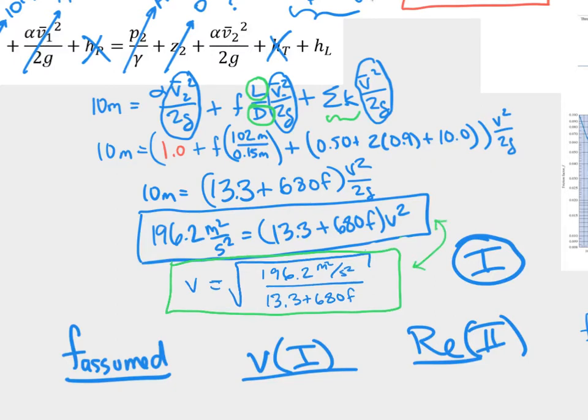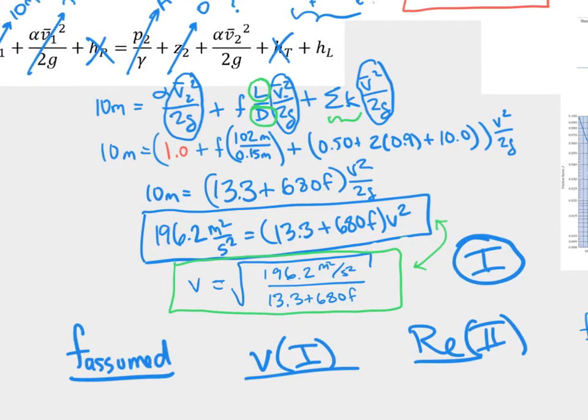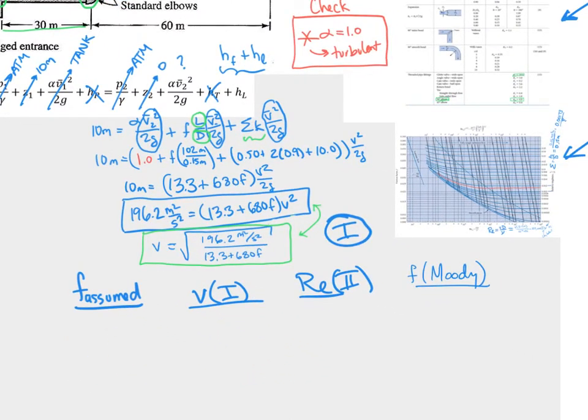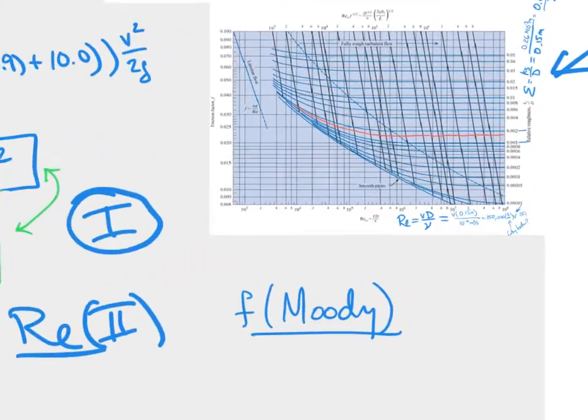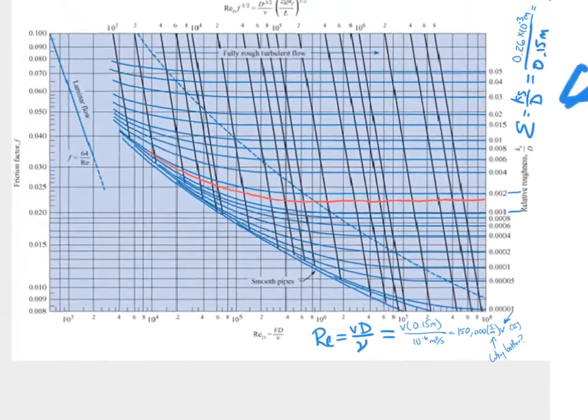So we'll assume an F. We'll use equation 1, and that'll give us V. Once we have V, we'll plug that into the Reynolds number equation, which we have deemed 2, although it's a little tiny on this screen. And then once we have a Reynolds number, we'll have both the Reynolds number and the...